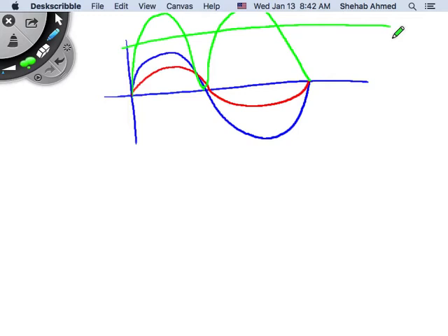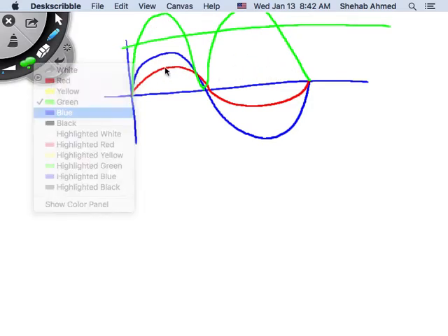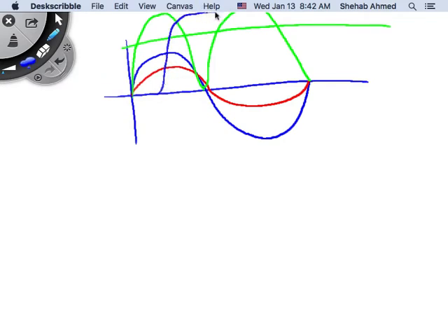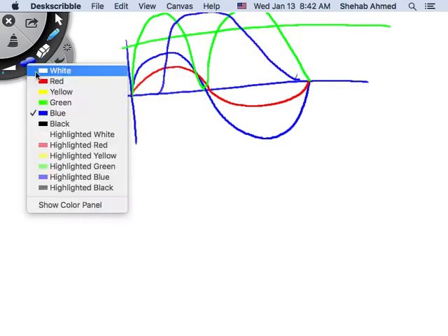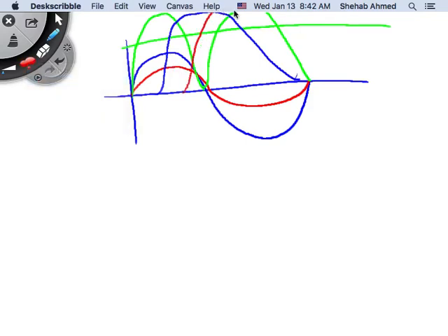In three-phase, I'm not going to attempt to draw it. People that took 438, no, I don't draw three-phase. I typically have a piece of paper that has it pre-drawn, and then I delete and cut it. It's too complicated. But in three-phase, it's like having three of those, but phase shifted. So can you imagine having this one and then another one here, and then maybe another one as well here, for example. So it's constant power, and we will do the math to prove it. But yes, power in three-phase is constant, right? So I have pulsating power versus constant power.